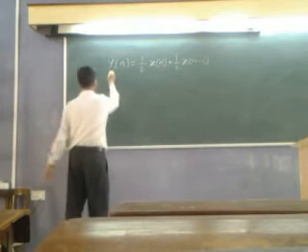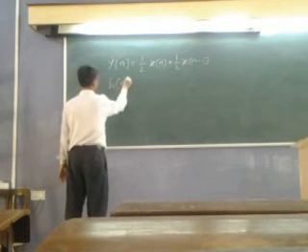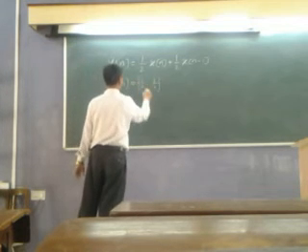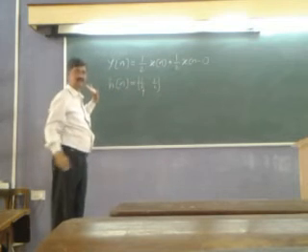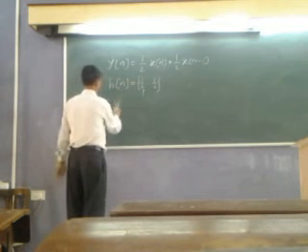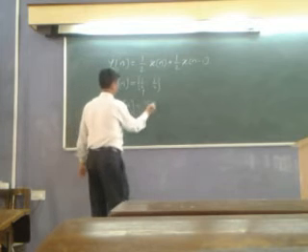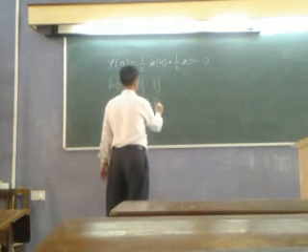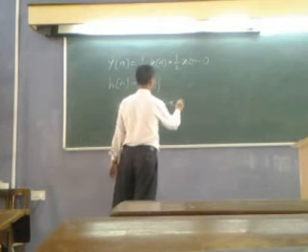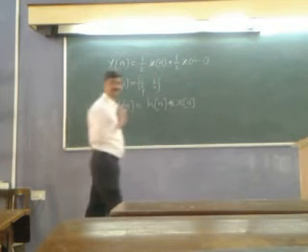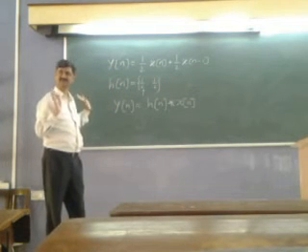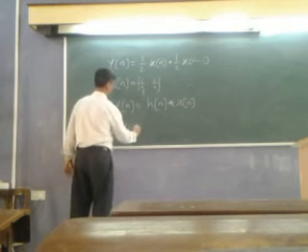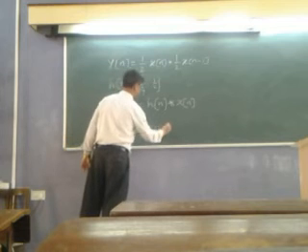This means that hn is equal to half, and ultimately the equation I can now write as the convolution of hn with xn. As it is a convolution, what I must have is Yz is equal to Hz into Xz.